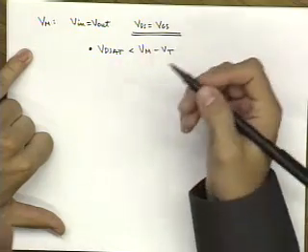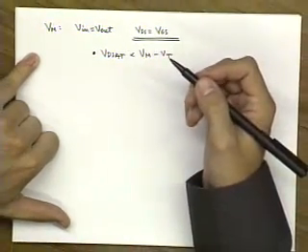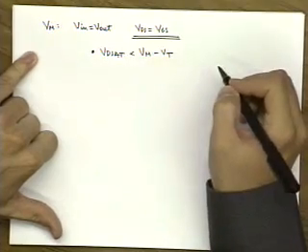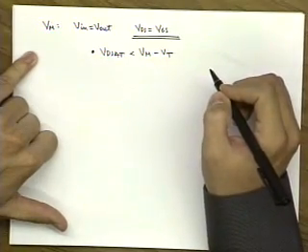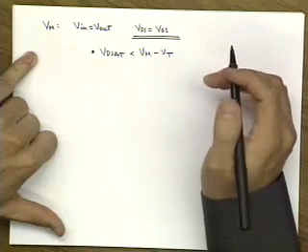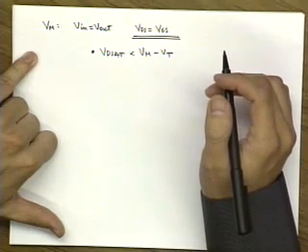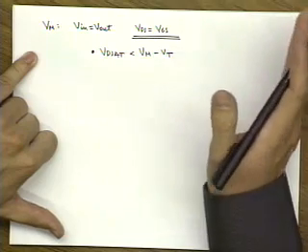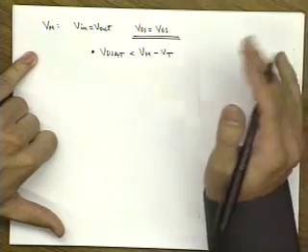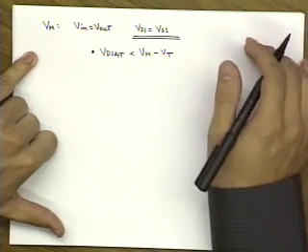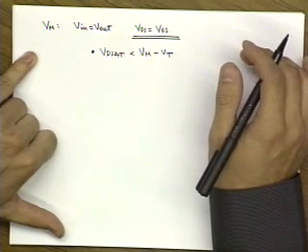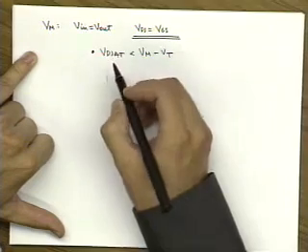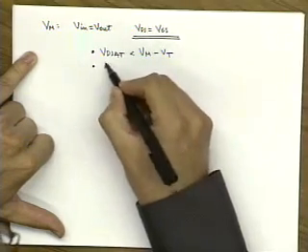That's still in velocity saturation at halfway between 0 and VDD. And this is a pretty valid assumption, because if you recall the numbers that we quoted, velocity saturation happens at about 0.5 volts or so. This is 1.25, so that's still a good assumption. So for the first order analysis, we can ignore channel length modulation.